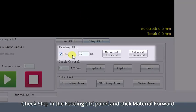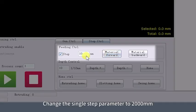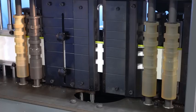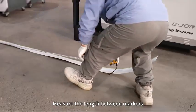Check step in the feeding control panel and click Material Forward. Make a starting mark. Change the single step parameter to 2000 mm. Click Material Forward. Waiting for feeding to stop. Make an end marker. Measure the lengths between markers.